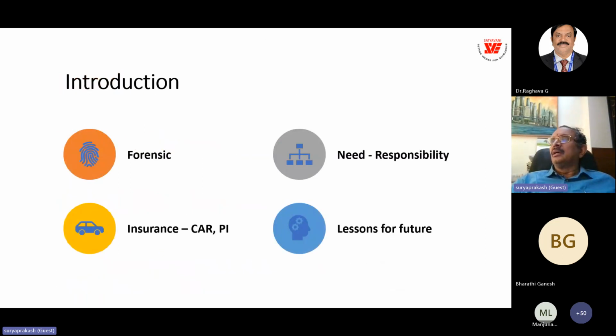Next, we should also be aware of forensic audit nowadays for any structure. As per the National Building Code, even a normal structure needs to be re-evaluated every 5 years to assess its stability and durability for its design, residual service life design period.